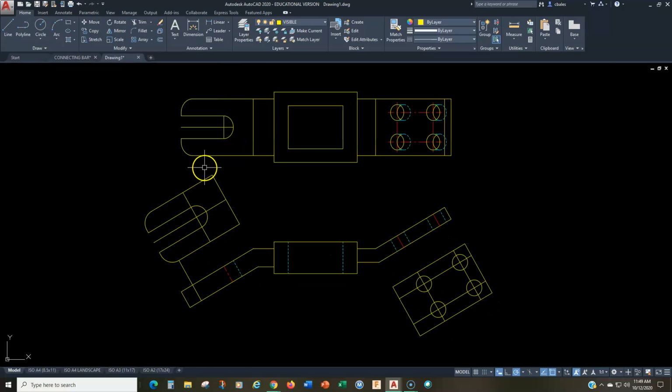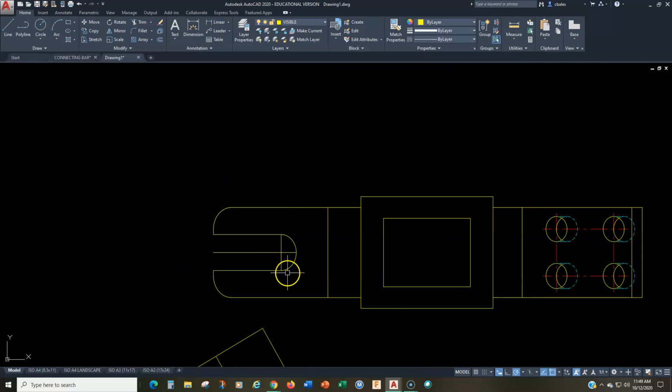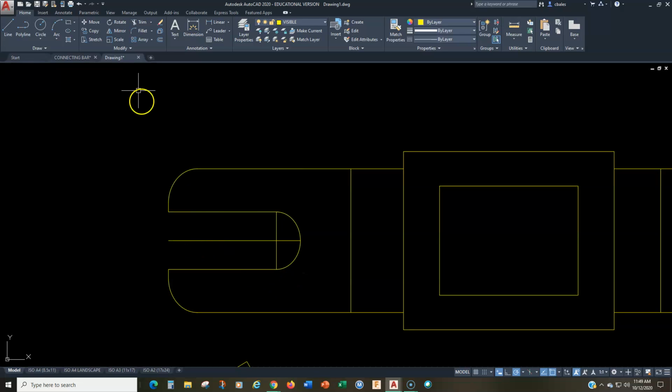Okay. So now I'm going to, whoops, and I can get rid of this. I'm just going to clean up a bit. Now, I can lengthen again. So we'll do lengthen. Delta 2 is still there. So that's going to be there and there and there. And then this is the lengthen 6 millimeters. So we go back to the lengthen command, delta 6. And we lengthen like that.